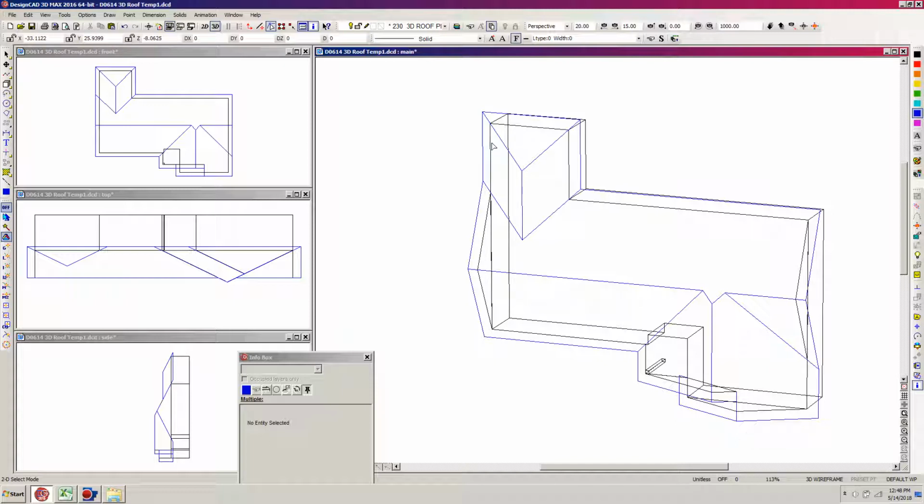So now what we're going to do is we want to extrude the roof. Okay, and so I'm assuming that we're going to be using, in this particular case, 2x6 top chords of the trusses. Allows us to put a much heavier fascia board on, a little thicker. And so I don't really know what the plumb depth is on the edge of the fascia if we're using 2x6s and then 5/8 inch roof sheathing. The total thickness is 6 1/8 inches.